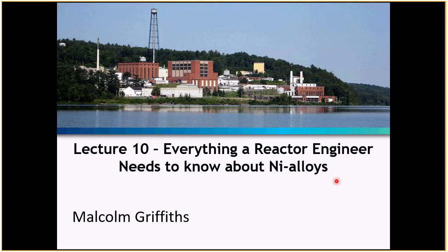But when people put these components in reactors, they really had no appreciation, or didn't think through, what long-term operation in a nuclear reactor core, especially a reactor core with a high thermal neutron flux, does to nickel alloys. There were some classic papers that came out in the early to mid 80s, principally by a guy called Larry Greenwood.